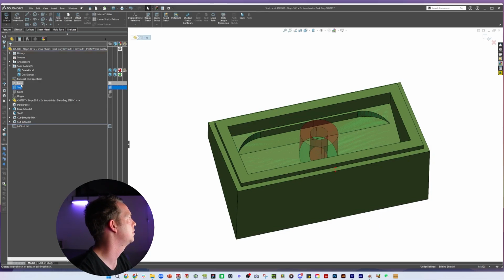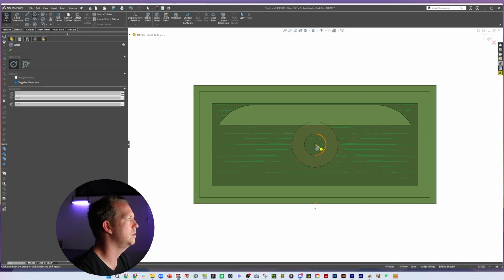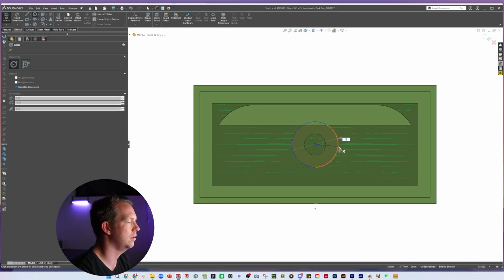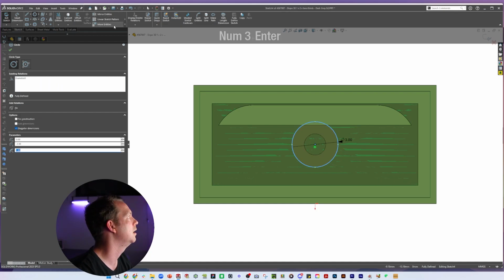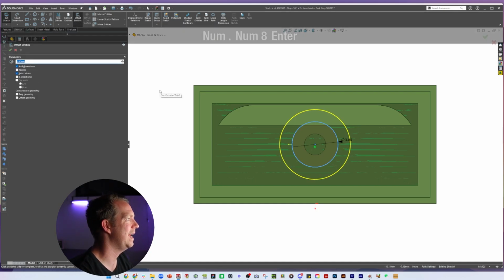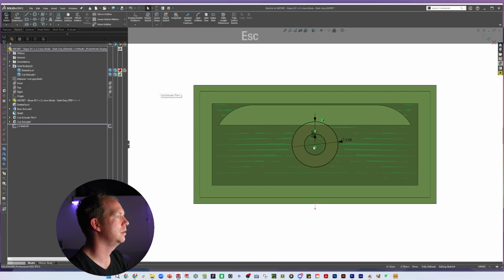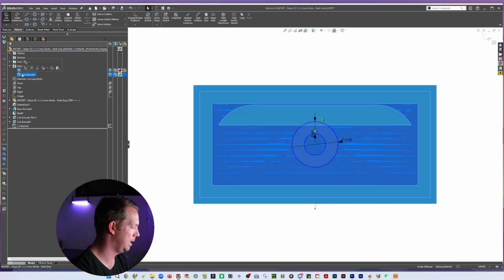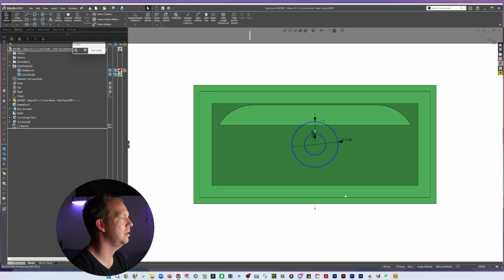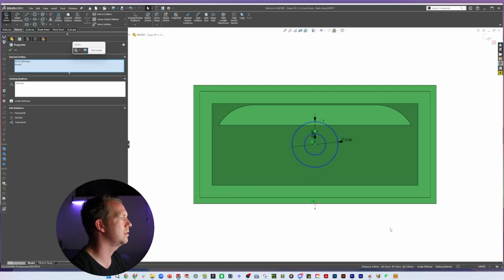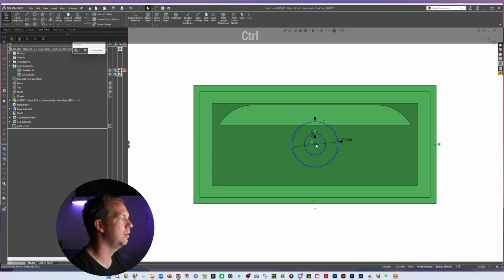All right, last step, well, second last step: create this pin on the bottom. So the top plane, we can use these for reference. So it is 3, and then I believe it's going to be like 0.8 offset. That's good. Delete that relation, isolate so we're only seeing the body we need, and then use references to that body and not the other one that we're about to delete.